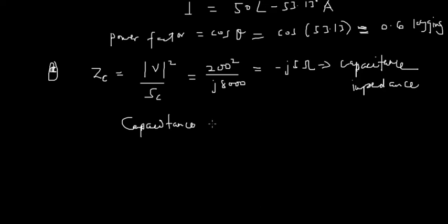Our capacitance is equal to 10 exponent 6 divided by 2 pi times 60 times 5. In case you remember this formula, that's good. In case you don't, you could check out our video on impedance, capacitance, and inductance. That's how you're able to come up with the capacitance formula and their respective parameters.